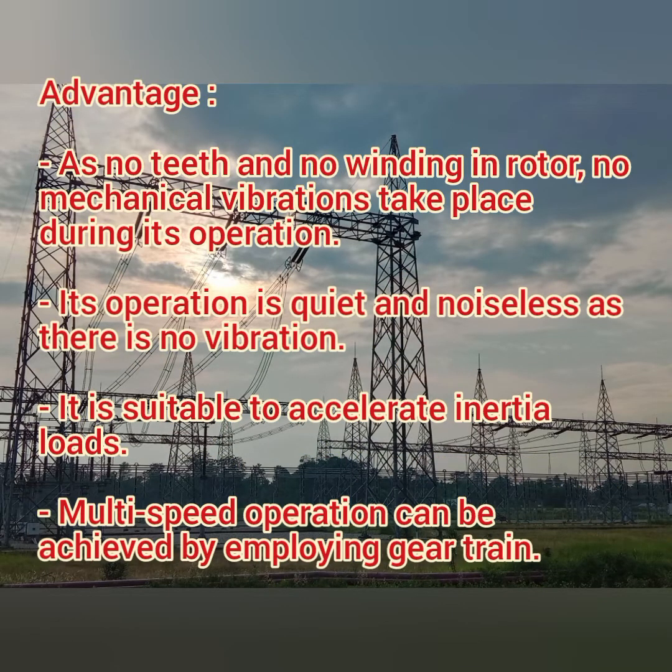Next, coming to the advantages of the hysteresis motor. As there are no teeth and no winding in the rotor, no mechanical vibrations take place in operation. Then its operation is quite noiseless as there is no vibration, and it is suitable to accelerate inertia loads. Then multi-speed operation can be achieved easily by employing gear trains.